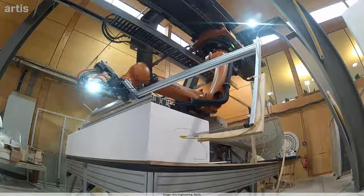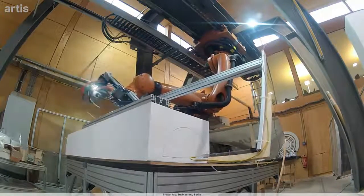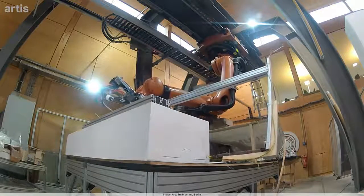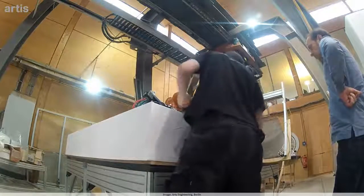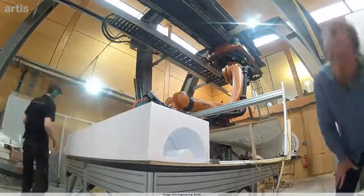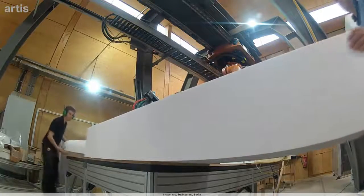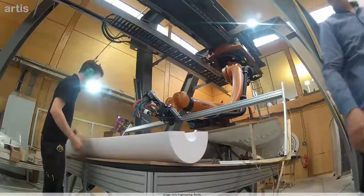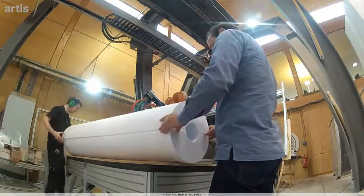And if you do this by milling, you would have to cut away everything that's basically here. So this takes very long and produces waste and all the other kinds of problems. If you do this by hot wire cutting, you see in 5 minutes you cut through, and with this geometry you can very quickly and efficiently fabricate it. Now the thing is, there is really no software for hot wire cutting. So again, for them the idea was they built their own hot wire cutter just out of aluminum profiles and a wire, and then created their own software tools, and bringing that together, they had a completely new solution.